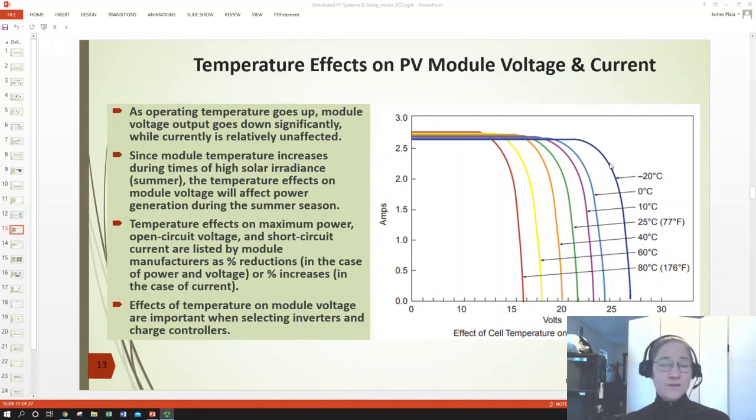If you want to give yourself a source of power in the winter, know that the voltage that your cells are going to be providing to your inverter is going to be much more than what you would have predicted from STC, and certainly more than summer. So your inverter has to have a wide range of voltage inputs so that it can take advantage of all of the power you're generating in the summer, but you might be generating at a lower voltage, but will also accept all of the voltage that you're getting associated with your power generation in the winter, when chances are you don't have a lot of photons hitting your panel and you probably don't need to be cutting your inverter off at all then either. And guess what?